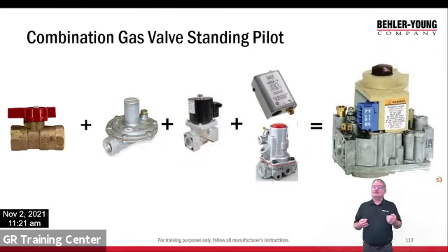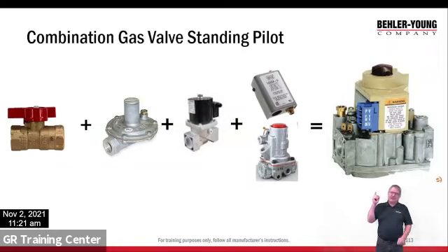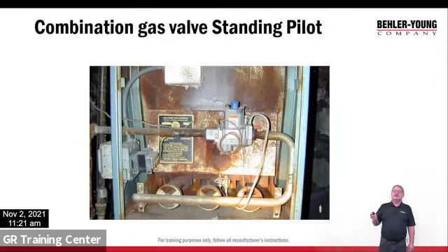Now you're going to hear the term combination gas valve. That's this guy. What that did is combine all that stuff together. So we got a pilot safety built in, we got a regulator built in, we got a shutoff valve built in, we have a main gas valve all built in. So now the thermocouple goes to it, the pilot goes to it.